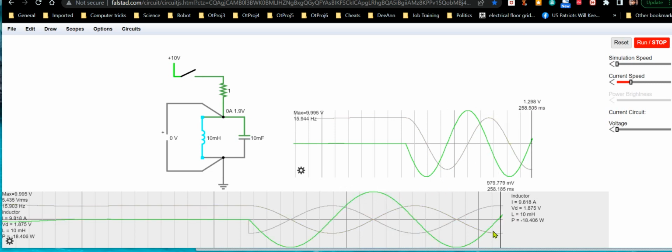But at any rate, that's pretty much what goes on in a resonant circuit, and why it resonates, and why these two aren't simultaneously charging, because they can't, because again, an inductor will override a capacitor's internal voltage while the inductor is charging up the capacitor. So that's why you see the voltage increase, but its current's falling off. But really, all you have to pay attention to is the inductor current and the capacitor voltage. And then once the voltage peaks, the current of the inductor reaches 0 and it's out of juice.